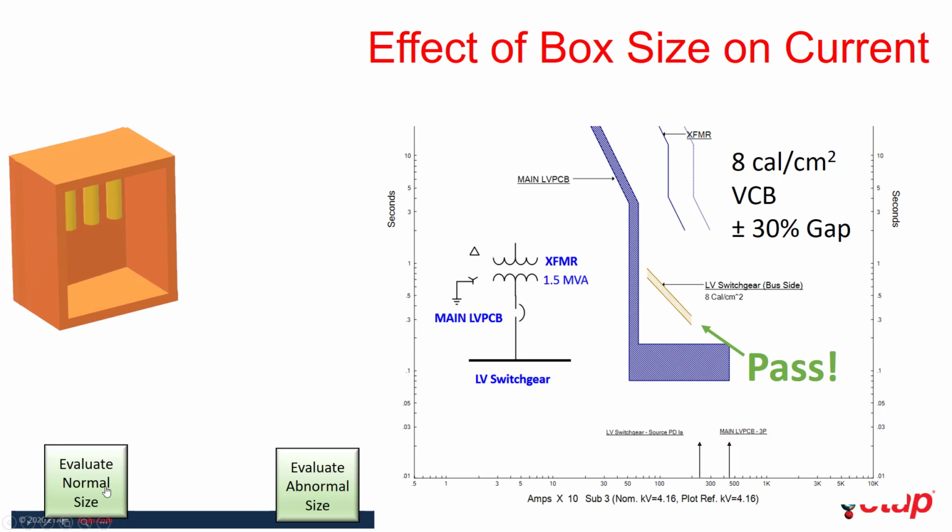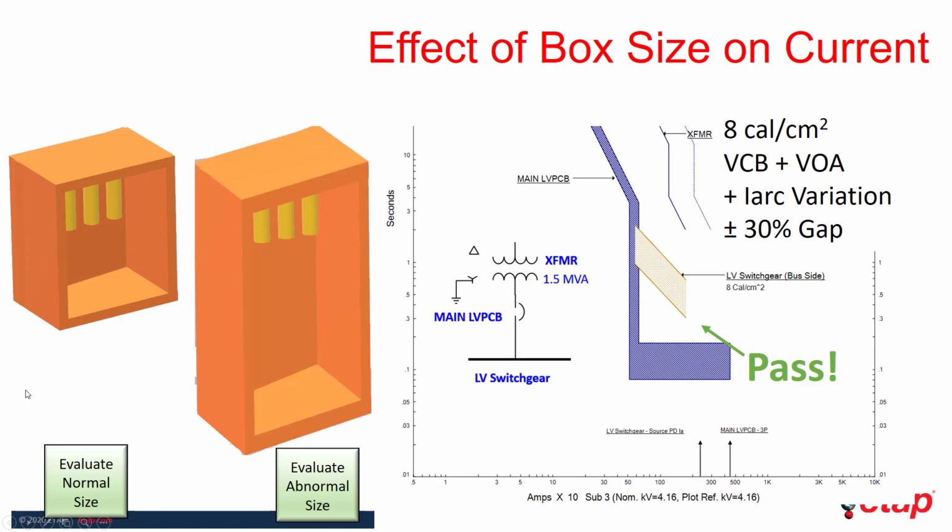However, what would happen if in fact this piece of equipment looked very different? What if those electrodes had a significant amount of space below, from the ends or tips of the electrodes down to the lower surface? This could potentially allow the arc columns to expand or elongate to a significant length. This elongation could make the actual arc current behave more like that current that you would get under a vertical open air condition. However, eventually the plasma cloud and the plasma will build up inside the enclosure and come out the front. So therefore the energy release would still behave like that of a box.